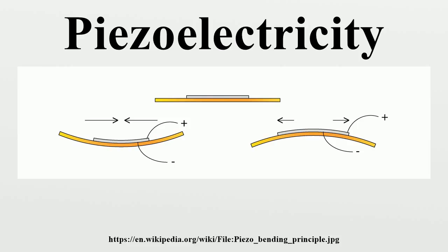Of decisive importance for the piezoelectric effect is the change of polarization P when applying a mechanical stress. This might either be caused by a reconfiguration of the dipole-inducing surrounding or by reorientation of molecular dipole moments under the influence of the external stress. Piezoelectricity may then manifest in a variation of the polarization strength, its direction, or both, with the details depending on 1. the orientation of P within the crystal, 2. the crystal symmetry, and 3. the applied mechanical stress.